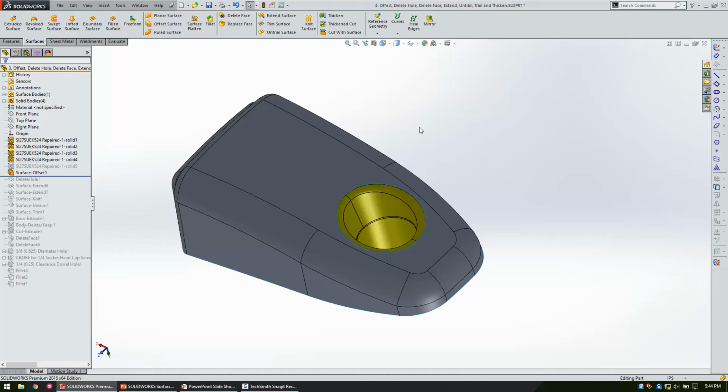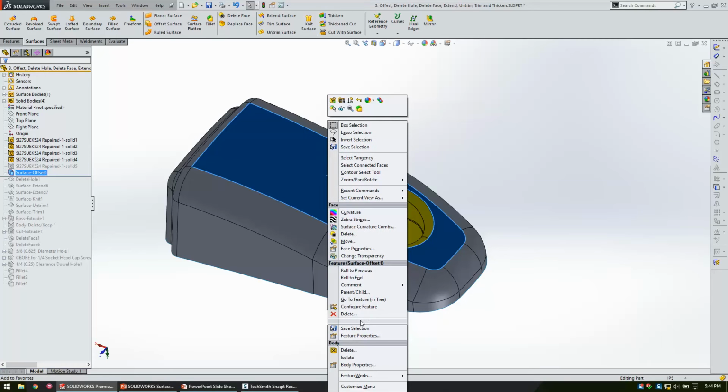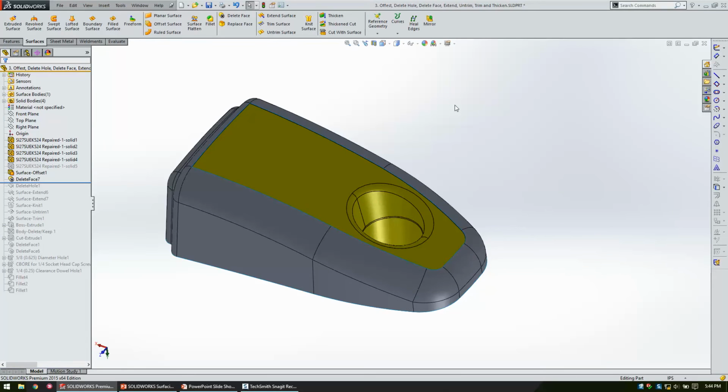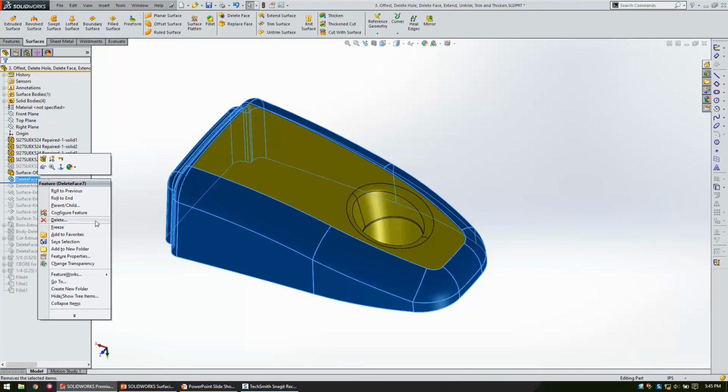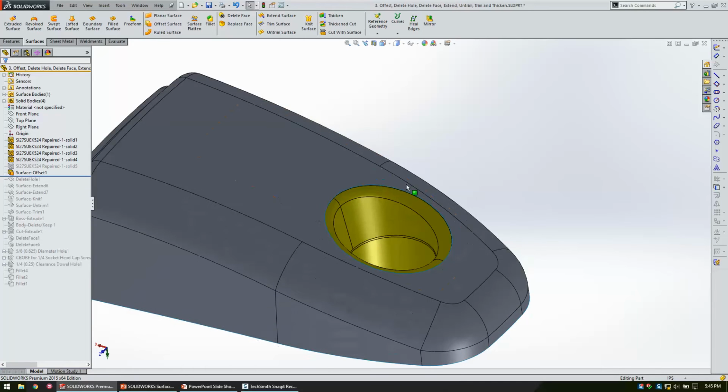Do a surface fill and fill it in? The delete face. So right click on here, and we're going to do a delete face and make it go away like that. All right. I'm sorry. I'm putting on my lecture hat, or my professor lecture hat a little bit and trying to get audience participation. If you guys don't like that, just let me know.